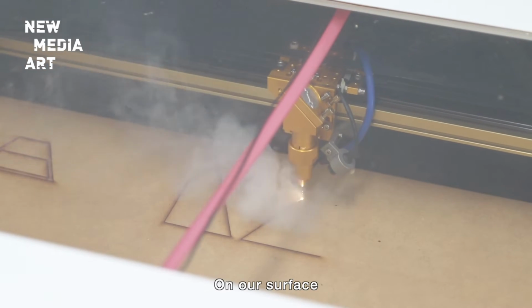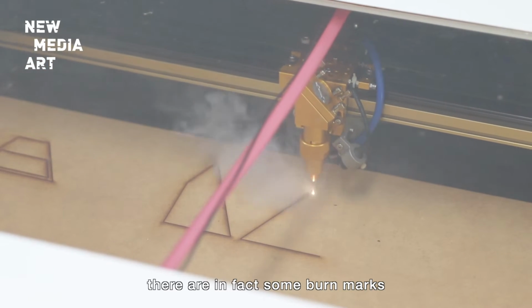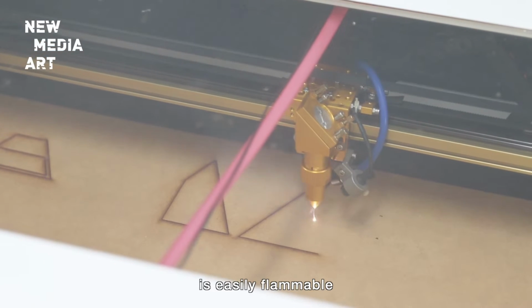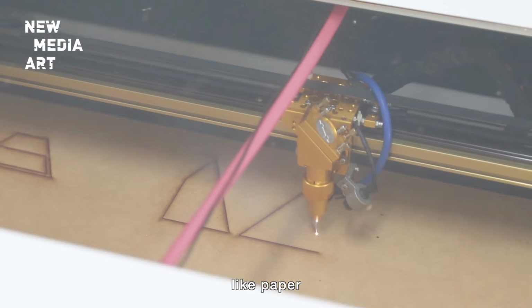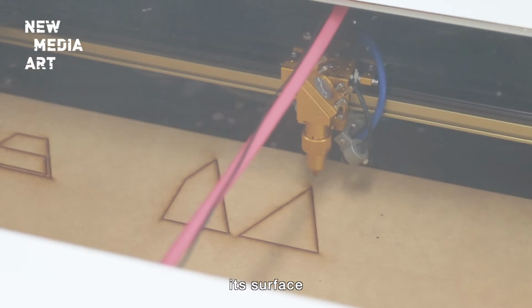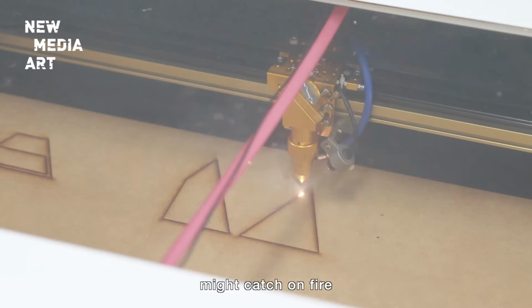On our surface, there are in fact some burn marks. This time as well, if the material you're cutting is easily flammable, like paper, then you can't set the power too high. Otherwise, its surface might catch on fire.